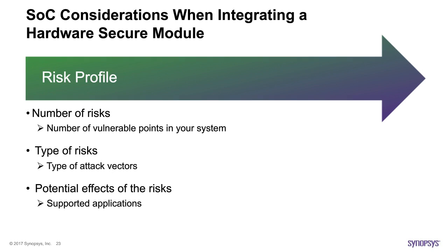For example, attacking a content protection protocol on a receiver. Allow it to fully authenticate with an upstream device. Once authenticated, it will begin to receive the protected content and place the unprotected content into a frame buffer. Now the attacker has access to the frame buffer memory and therefore can steal the content. So knowing the type of risk is important as it applies directly to the customer of the SoC and the context they plan to use it in.